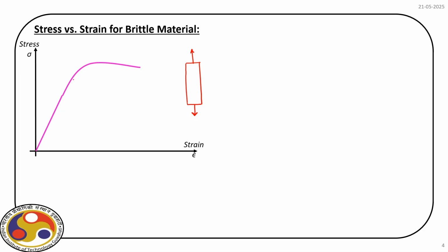Now, if we look at the stress strain behavior, we do not have a distinct yield point that we can notice from this plot. So, for this type of material, what do we do? We consider a point on the strain axis, as you can see on your screen, and then we draw a parallel line shown here by this dotted line, and we reach a point.